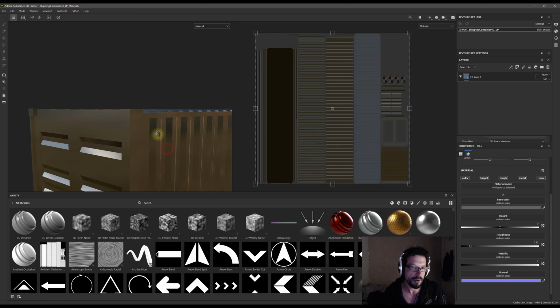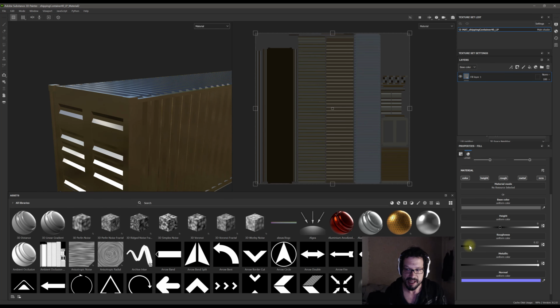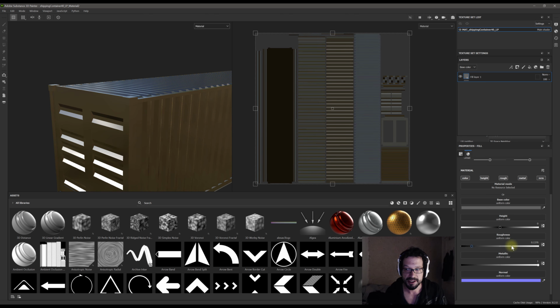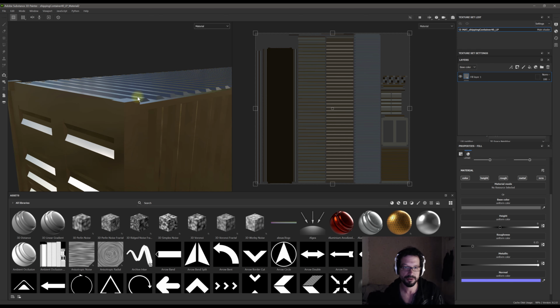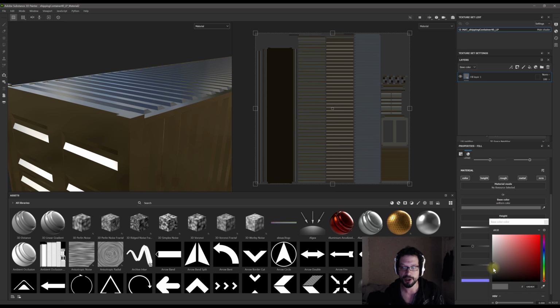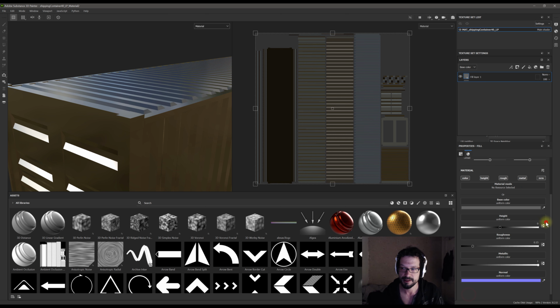Okay, so a very glossy surface. This is not fully glossy. Remember, this is not a mirror, but it is somewhat glossy. Like 0.15 I think is good. 0.12, 0.15 is good. And it's fully metallic with a middle tone to darkish gray. Okay? So that's it. This is the beginning point.